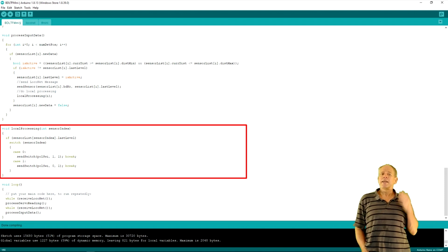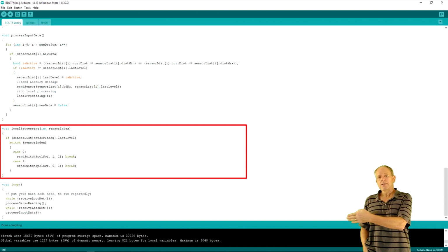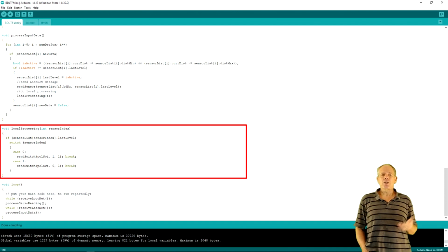This is actually an important principle when doing LocoNet messaging. You always should broadcast your messages first to LocoNet and only take action on the echo. That way you make sure that you only process messages that were successfully sent to all other nodes, and if there is no echo, you can react to the error and resend.